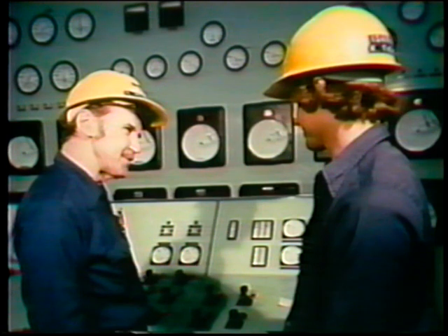Before troubleshooting the controller, it's important for the electrician to find out the symptoms of the problem. So first, he talks to the operator. The operator originally reported the problem, so he's the best person to describe it. The operator tells the electrician that the motor starts when the start button is pushed, but as soon as the start button is released, the motor stops. He also tells the electrician that as long as the start button is held in, the motor operates.